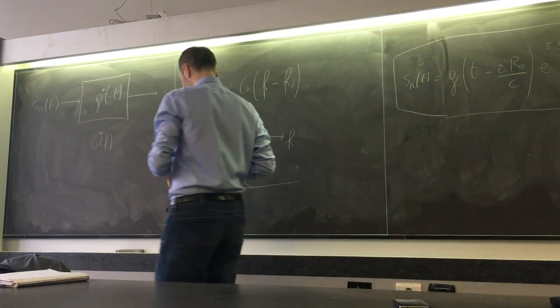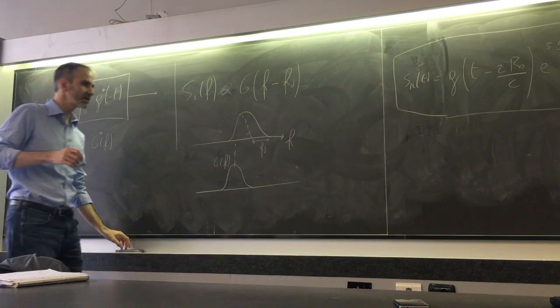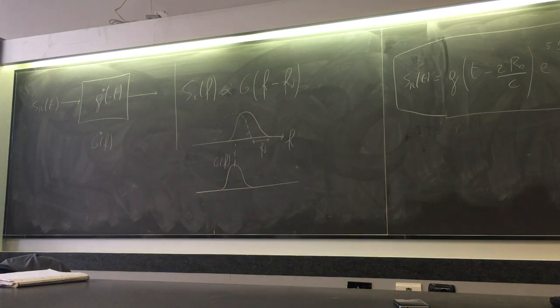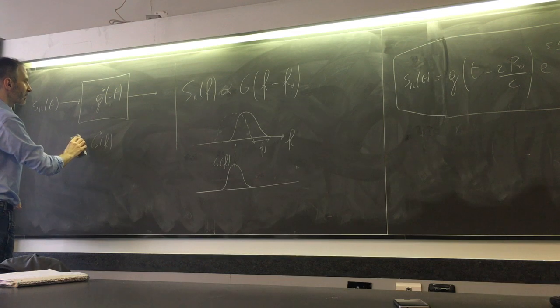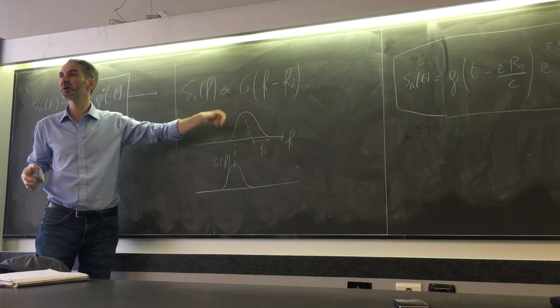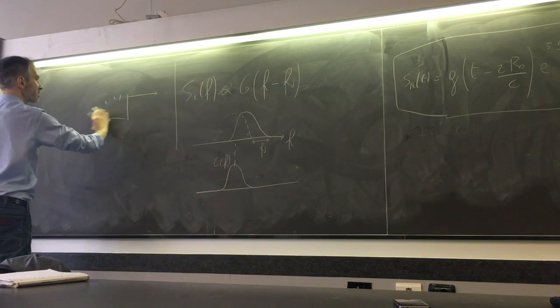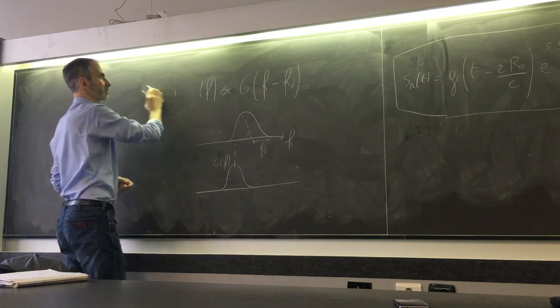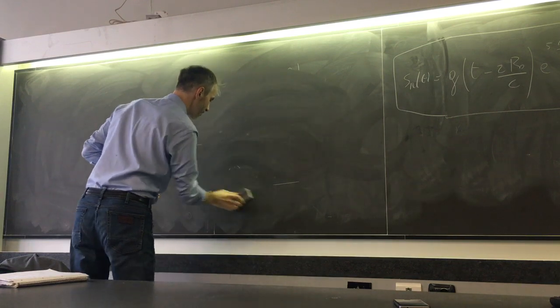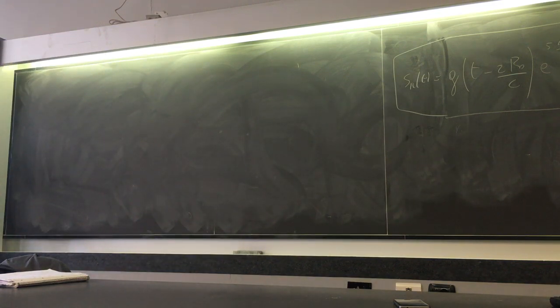So how do you deal with that? Well, I like to start from a very simple scheme, and since we have seen that the problem here is that the frequency is no longer matched, the idea could be to try to compensate for this frequency, and then do your matched filter. So the scheme of your receiver in the presence of the Doppler frequency would be something of this kind.